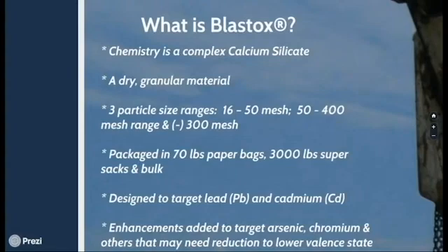It is a very finely graded material that's intended to be injected into ventilation systems, so the fine particle can be entrained so that it can commingle with materials or waste that are being generated from our foundry industry. Those smaller particles commingle with the dust coming through that ventilation system, so when they get into the baghouse, they're already thoroughly homogenized so that they can react with the heavy metals.